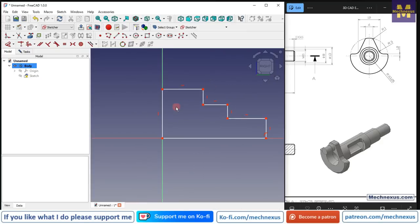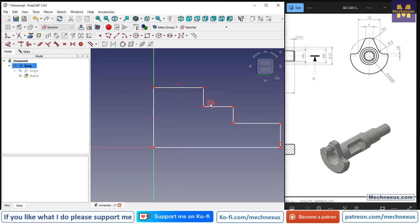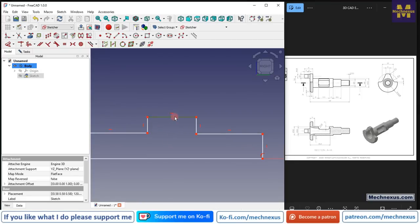So this is the rough profile, and now we will constrain it. So if you see in a FreeCAD version 1.0, once you drag the line, you will see the value. So here we will make it close to our requirement.